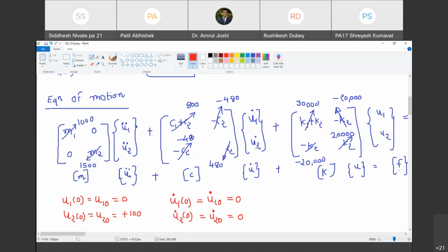ये equations अगर uncouple, decouple करने हैं तो क्या करना पड़ेगा? Somehow I must have this C2 term to be 0. Are you with me? Yes, sir. So therefore if even one of the K, C और M ये तीनों matrices non diagonal है, then we get coupled equations. Mind you, there was not much problem about the mass matrix because it is a lumped matrix.